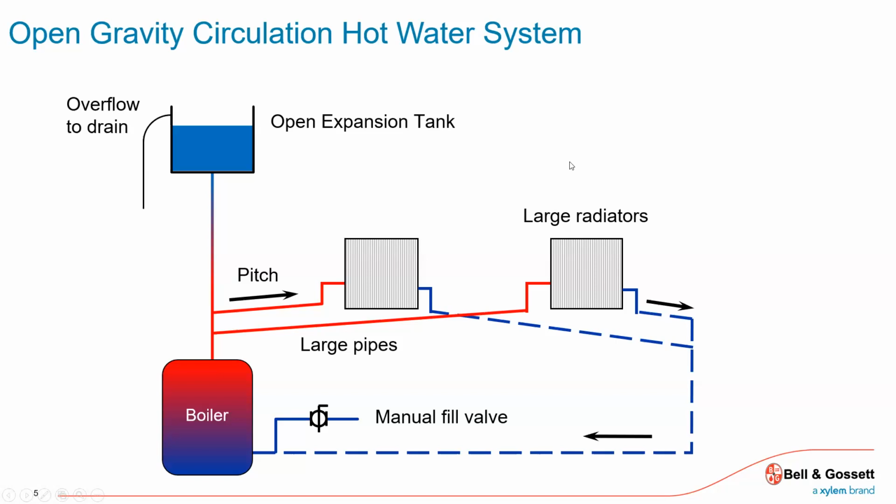They realized quickly that when you heated that coal-fired boiler and you heated the water and it expanded, you had to have a place to put it, or the boiler would explode because water's not compressible. You've got to have a place for that water. So years and years ago, it was just an open expansion tank at the very highest point of that church, that school, that house, that whatever it was, that building. And obviously no circulators because it was gravity.